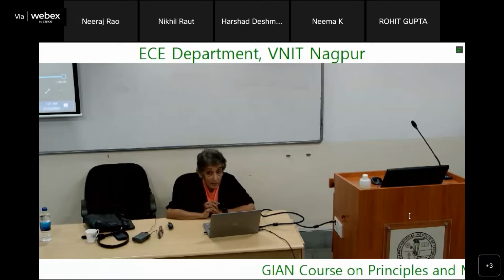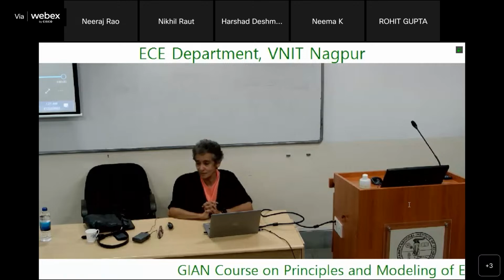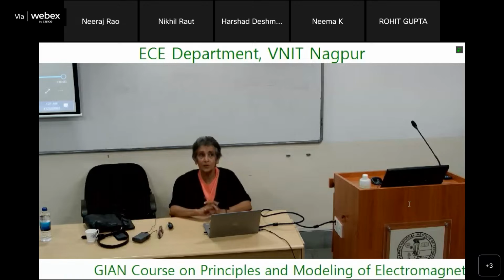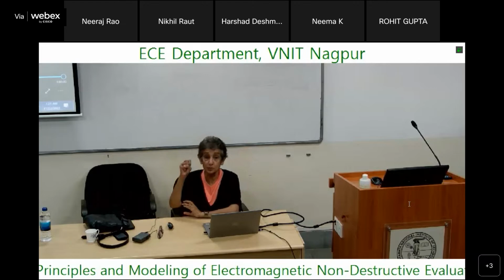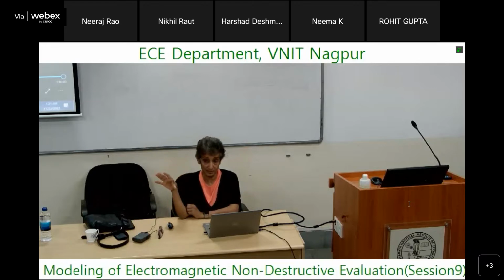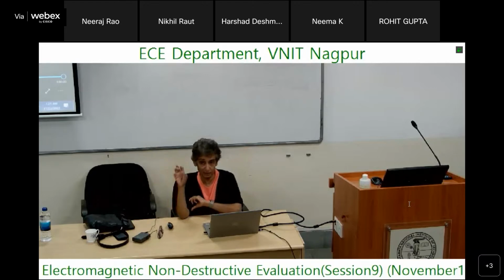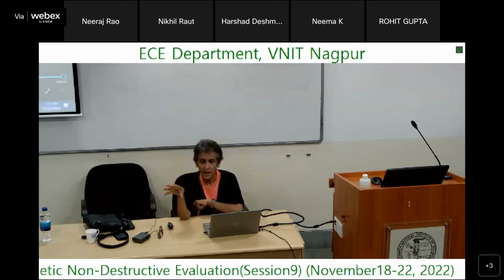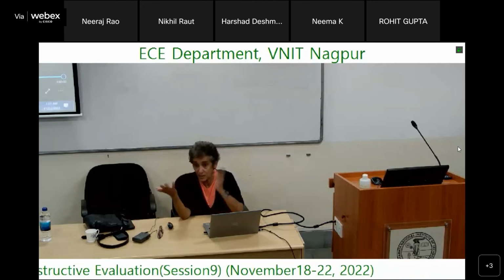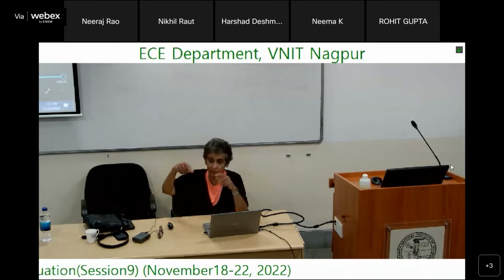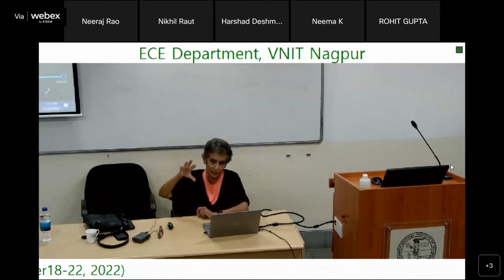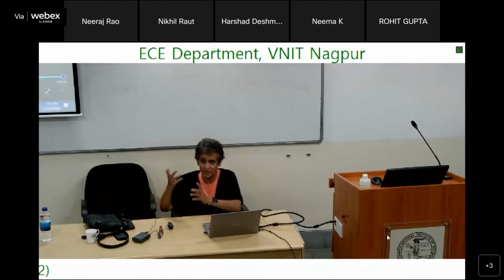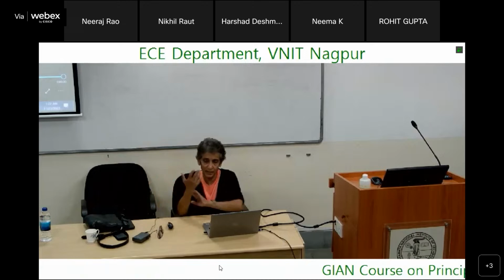About what? Oh, that's a full thesis. In the meshless model, basically you just put nodes. There are no elements. There's no mesh, but there are nodes only. And you have to have some kind of basis function. So every node has its sphere of influence, and with it you define some kind of a radially symmetric basis function. Okay.